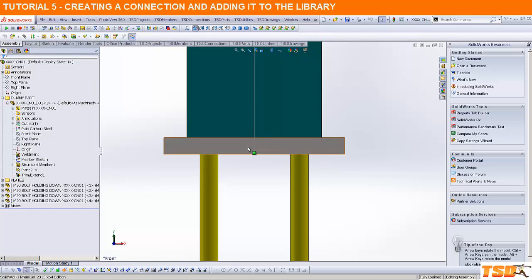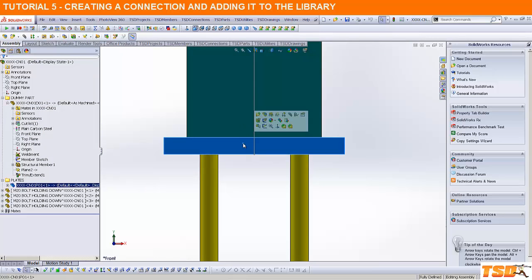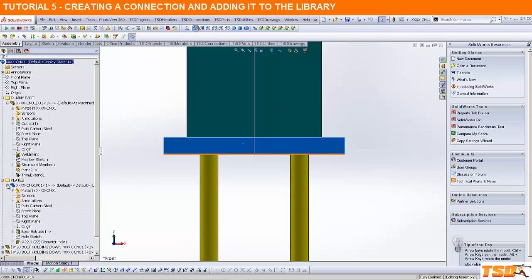Now if you want to add a grout part to that, you make the grout part a dummy part and exclude it from the bill of materials. I'm not going to show you that, but you can. Now to position this so that it's not on origin, and I'm going to give myself enough room for grout because grouting is stock standard in a lot of scenarios, I'm going to use a different mating process to position that.